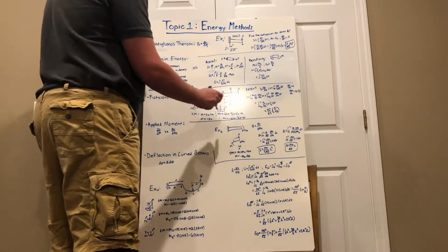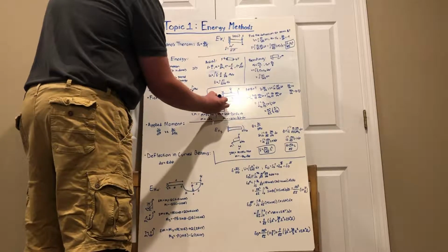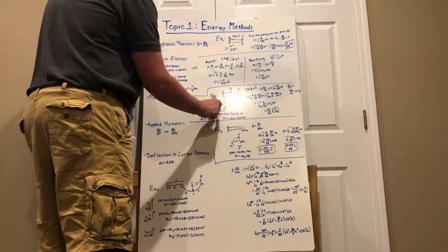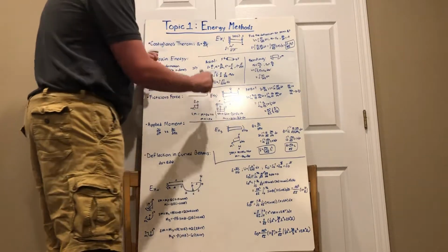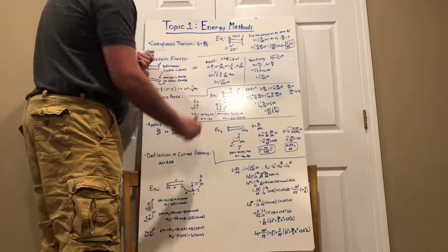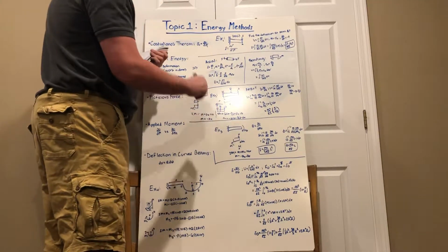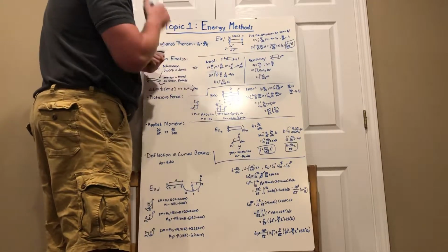Or in this case, what we're doing is we're subtracting it from this entire length. We're calling this x. And we're going to subtract this distance because it's already known. We only care about this one. Then we're going to add p times this x distance to this cut, and we're going to set that equal to 0. Rearranging, we get our moment is negative q times x minus L over 2 minus px.